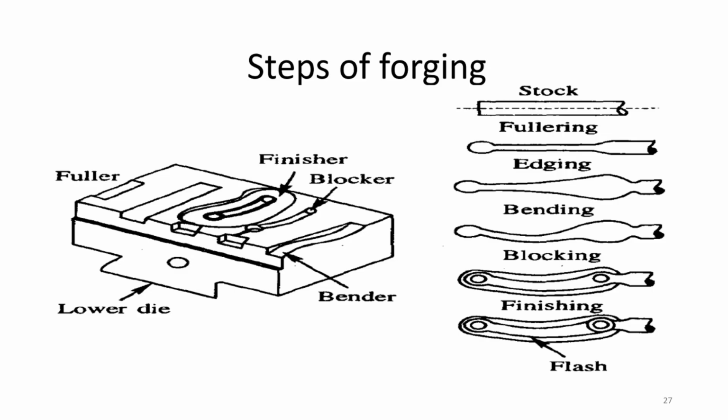Solid shrinkage and solidification are both different, isn't it? Solidification is the process when your liquid is converting into solid. Solidification is not any shrinkage. Solidification is the process of converting liquid into solid in case of metal, or it can be in case of water or anything. It is not a defect.